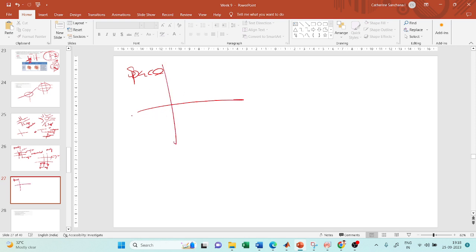They can cross each other at the same time, right? Vehicles traveling on this road can travel at the same time as the vehicles which travel on this road, right? But they are separated by space. That is why they do not have any conflict. They can travel without having any conflict. So that is a space separated intersection.